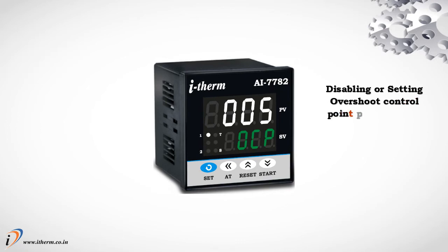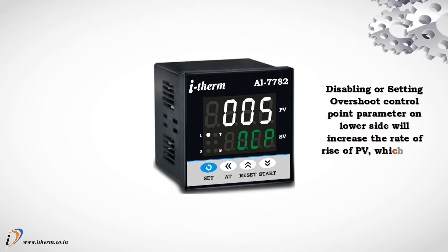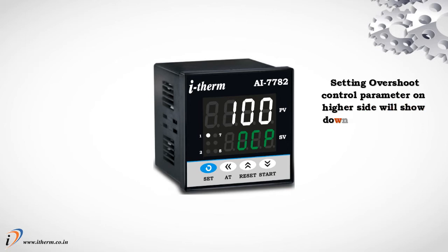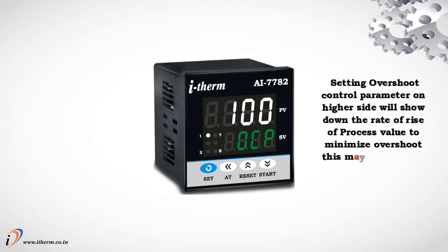Disabling or setting the overshoot control point parameter on the lower side will increase the rate of rise of process value, which may cause overshoot. Setting the overshoot control parameter on the higher side will slow down the rate of rise of process value to minimize overshoot. This may cause a delay to reach set point.